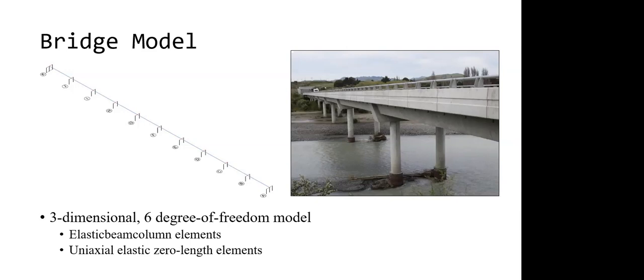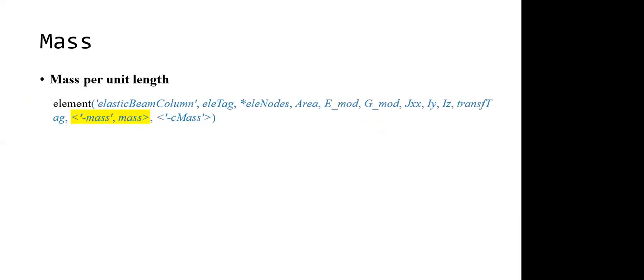Okay, cool. Now, linkage. When you said the mass, there is another thing which a lot of people will miss. We had a discussion. When you're distributing your mass like this, how does OpenSees calculate the mass distribution? So this mass is a distributed mass. This is the mass per unit length of the element, whether it's a column or beam.